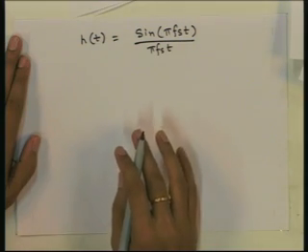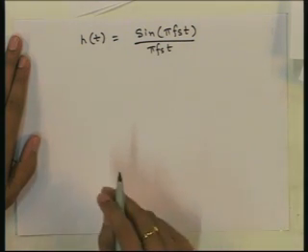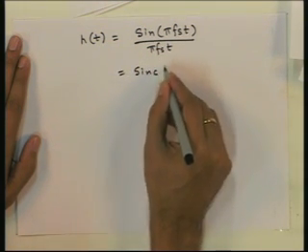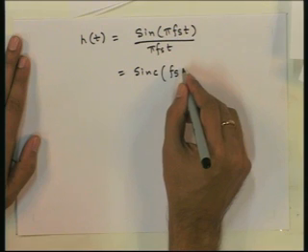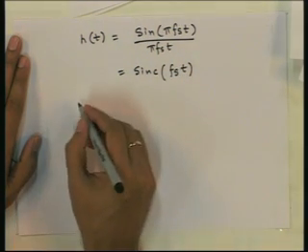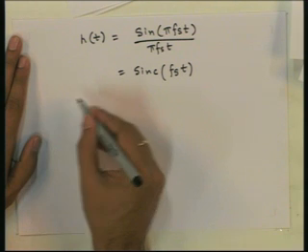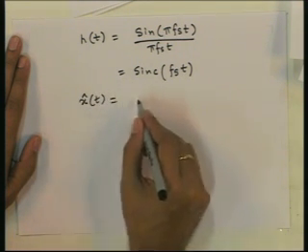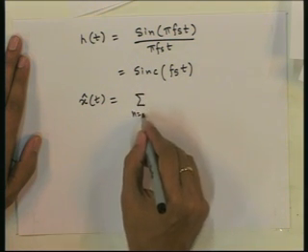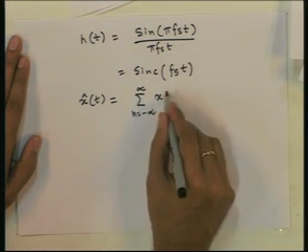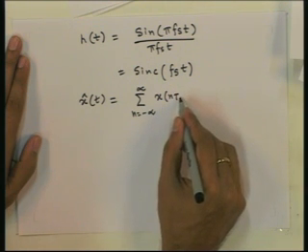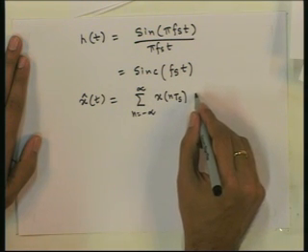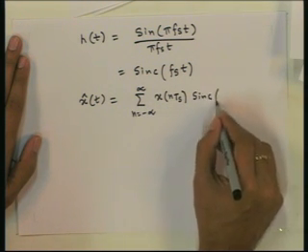If the original signal was band limited and the sampling frequency was greater than the Nyquist rate, we will see that now. So this is nothing but sinc Fs t, and then the recovered signal at the output of the filter is x hat t. These are the sample values, and then the shifted impulse response.